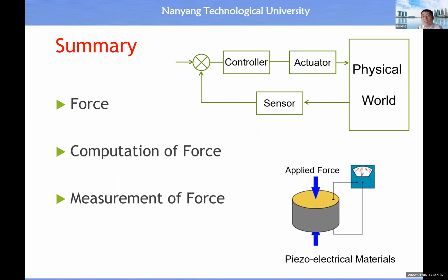So here, basically, we know we can make use of a sensor element which could directly convert force into voltage. Second, the principle for us to follow is to do conversion from force to resistance, then conversion from resistance to voltage. In this way, we could leverage the use of a microcontroller to support the implementation of a measurement and sensing system for force.